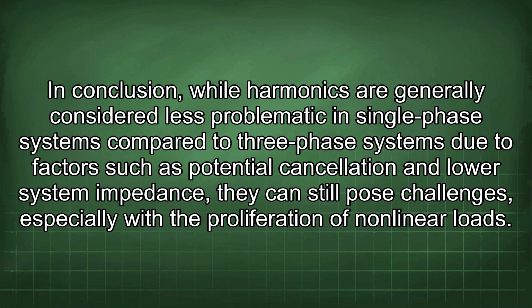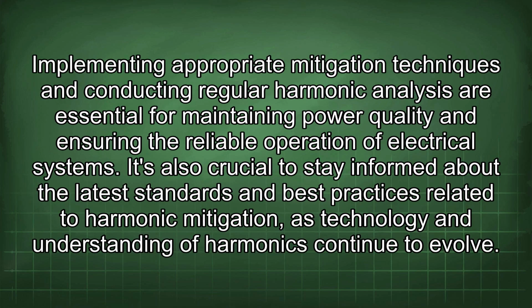In conclusion, while harmonics are generally considered less problematic in single-phase systems compared to three-phase systems due to factors such as potential cancellation and lower system impedance, they can still pose challenges, especially with the proliferation of nonlinear loads. Implementing appropriate mitigation techniques and conducting regular harmonic analysis are essential for maintaining power quality and ensuring the reliable operation of electrical systems. It's also crucial to stay informed about the latest standards and best practices related to harmonic mitigation, as technology and understanding of harmonics continue to evolve.